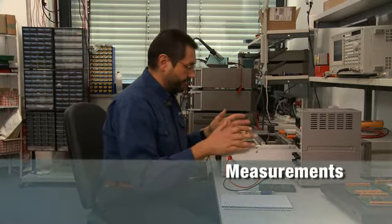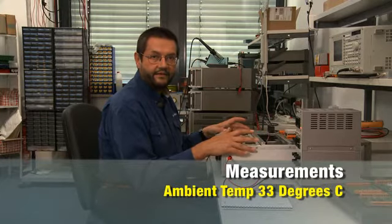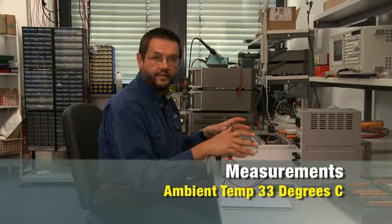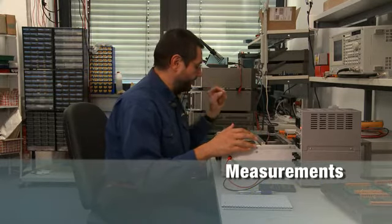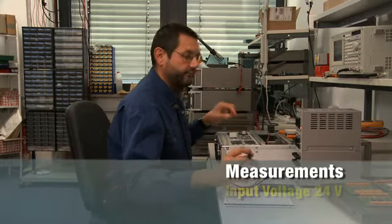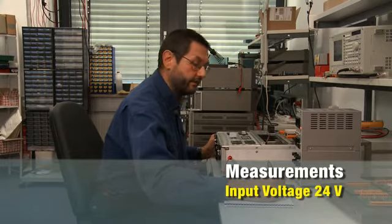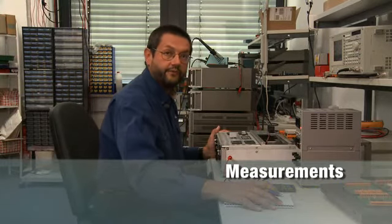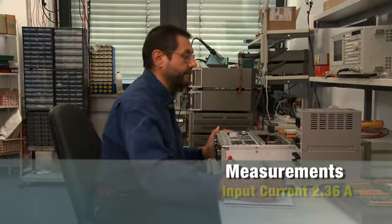Our ambient temperature is now 33 degrees C, therefore we can keep that as a starting point and see what the temperature increase will be. We'll switch on the module now, and we can set up the input voltage to exactly 24 volt. It's very important to make a precise reading of the displays in order to have an accurate calculation of the efficiency.